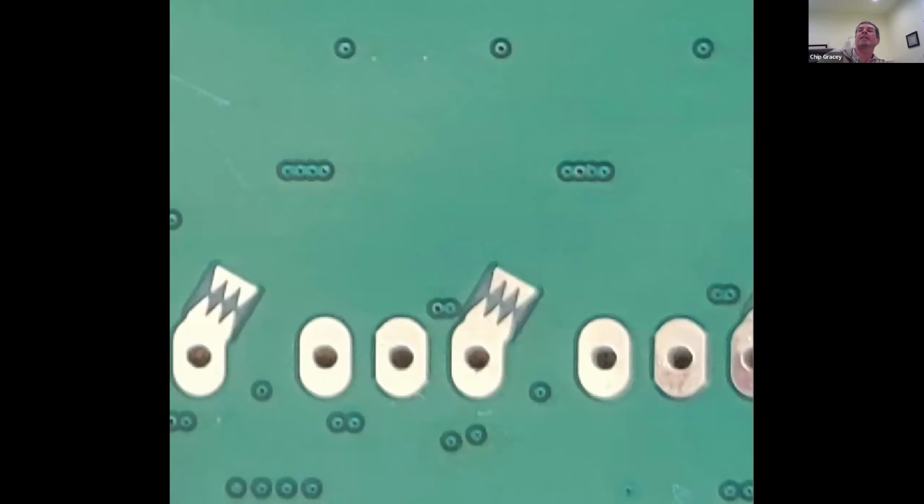I think the reason it said to pull back the solder mask was that you want some third dimension in this thing, where you want those little points to be elevated and pointing towards each other. Then when it runs over the selective soldering machine, it's going to deposit more solder onto those and build them up, which could initiate the arc earlier and provide a higher cycle life, because you're not just chewing through this thin copper.